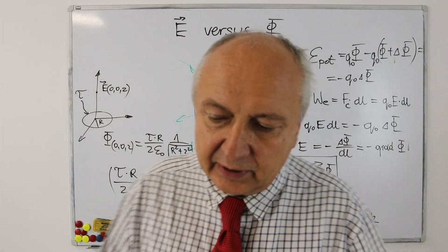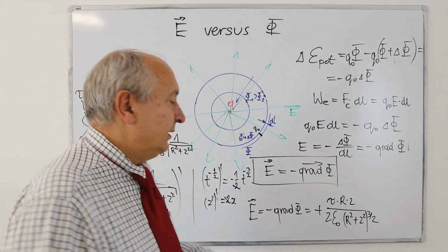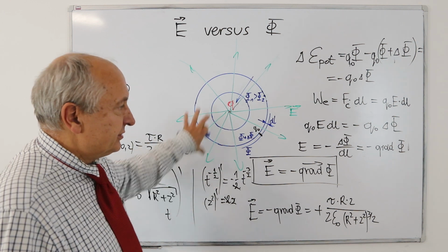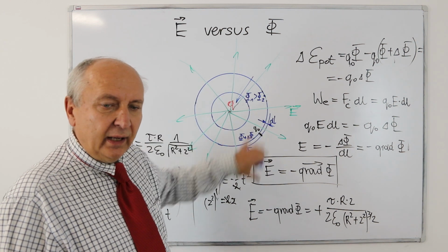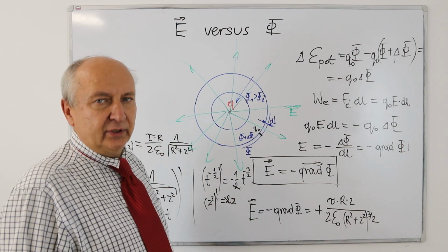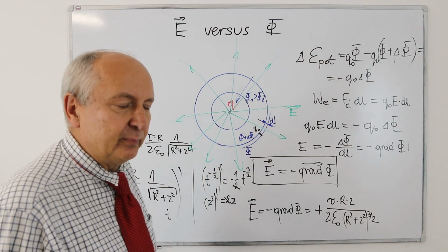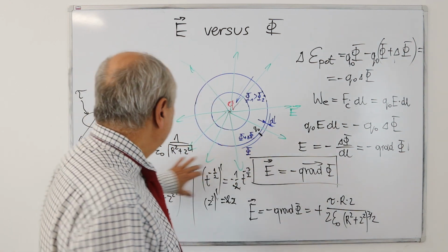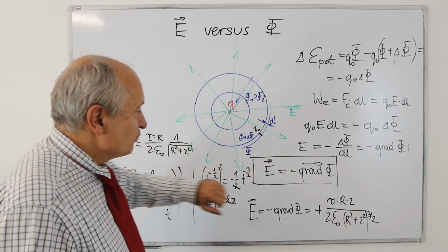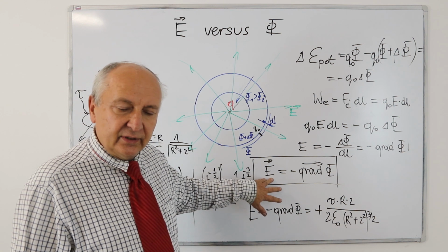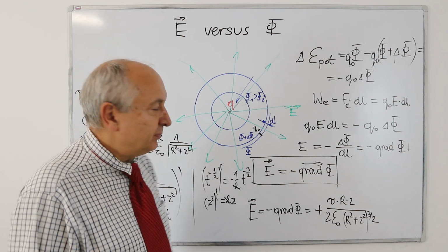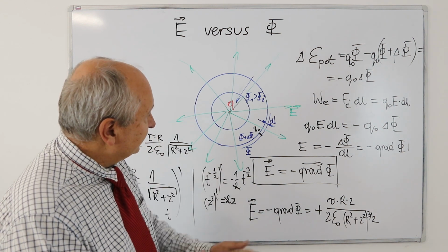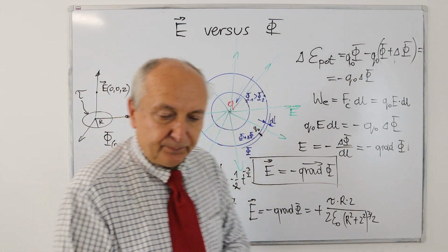And this is the way of calculation. Numerically, firstly we find the potential distribution in the field, and when we know the function that describes the potential distribution, we can, using the gradient, calculate the electric field intensity. This is the simplest way of finding the electric field intensity.